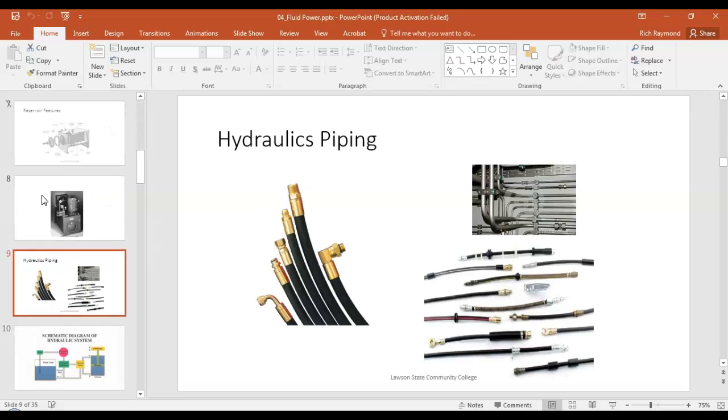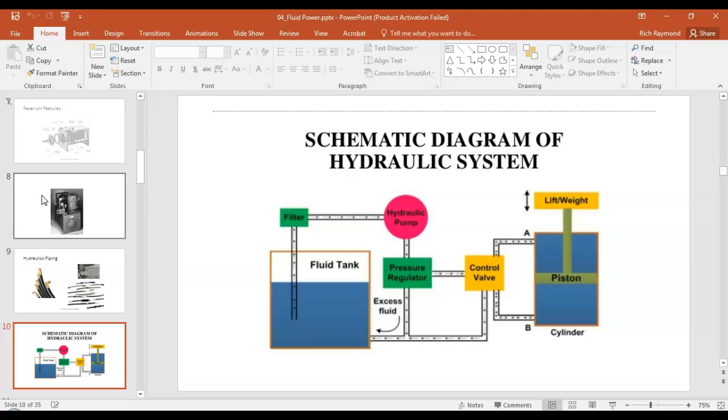And we looked at the parts of a hydraulic system. So this is a basic hydraulic system. Normally, what they don't show on this one though, we usually always have what we call a pressure relief valve on this. A hydraulic system would have the tank, a pump, a regulator, control valves, and then some type of actuator out here. So an actuator is anything that takes these pressures and converts it into motion, right?